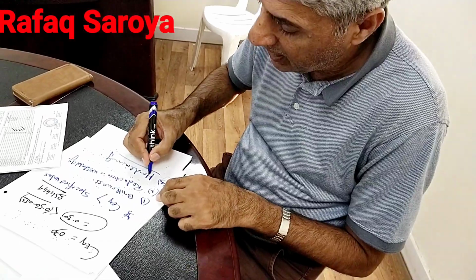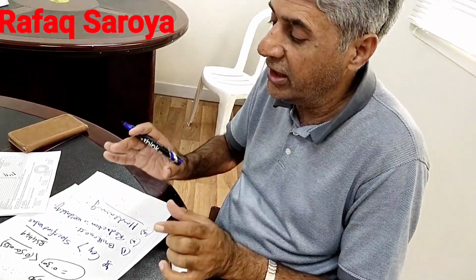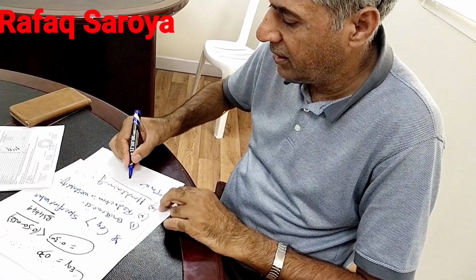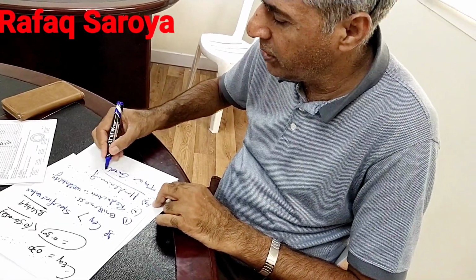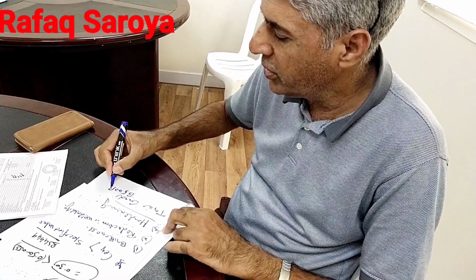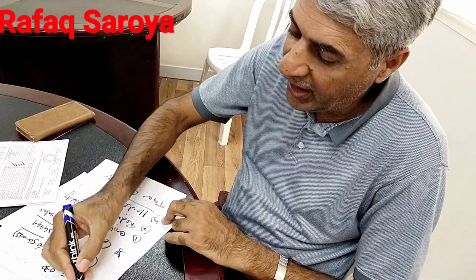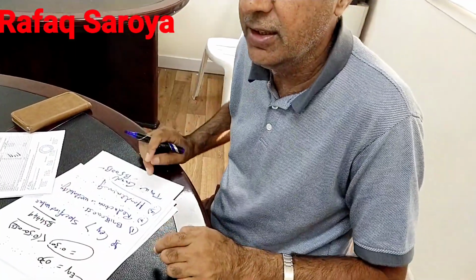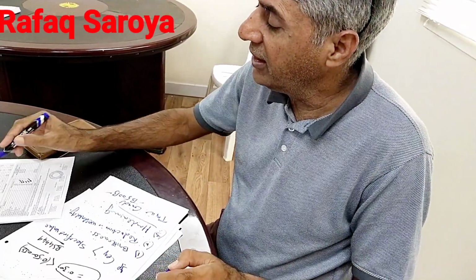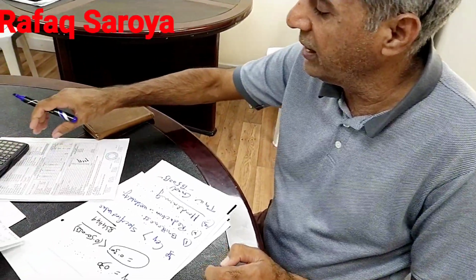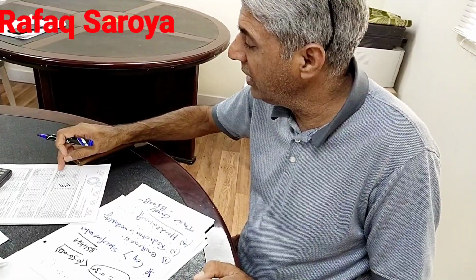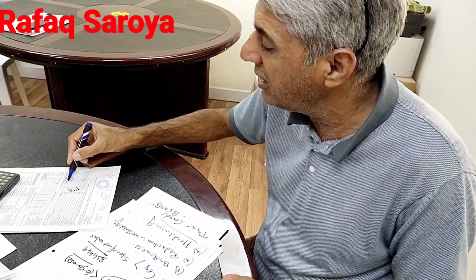So that is why, in order for the steel to be the true grade B500B, it should satisfy this combined chemical property and its individual chemical properties. When the test report comes in front of you, you will have to check whether these properties comply with our specification or not.